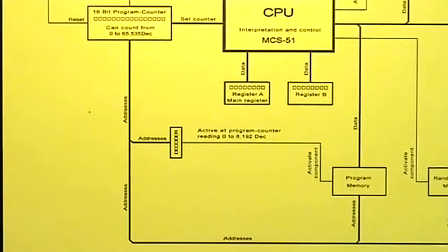This jump command, respectively this instruction, is 00000010 binary at the MCS51 core and is an unconditional long jump.